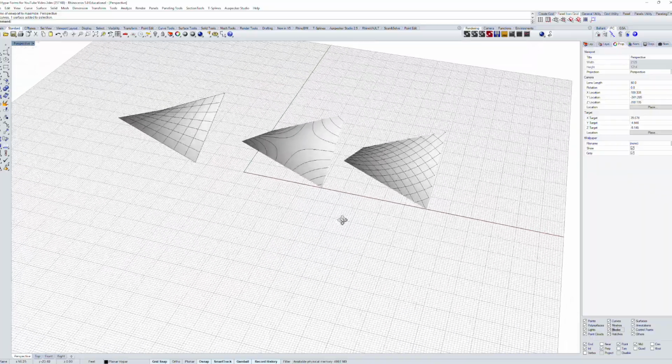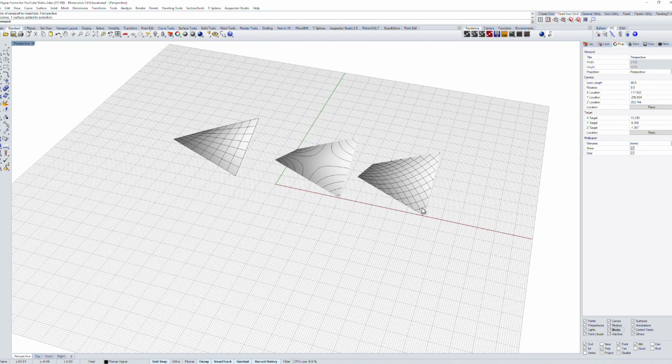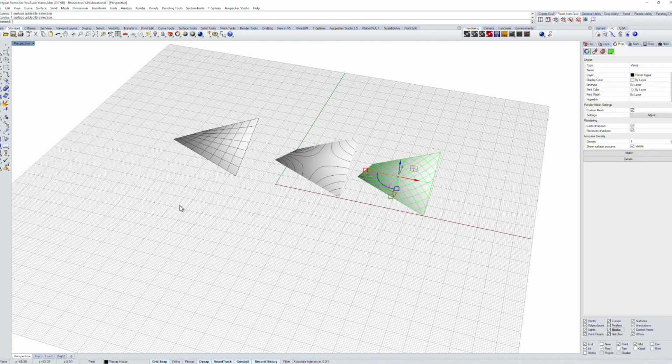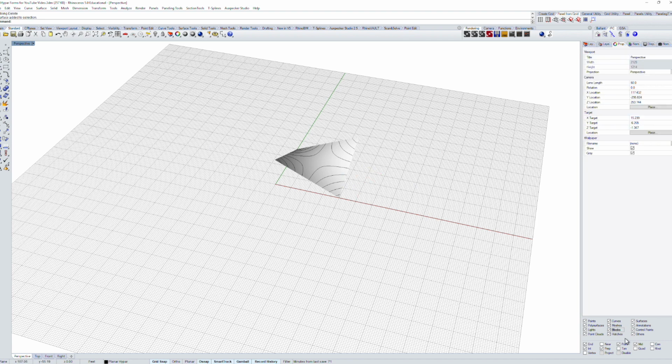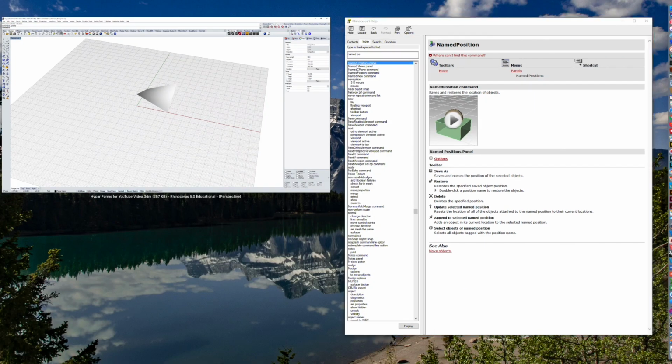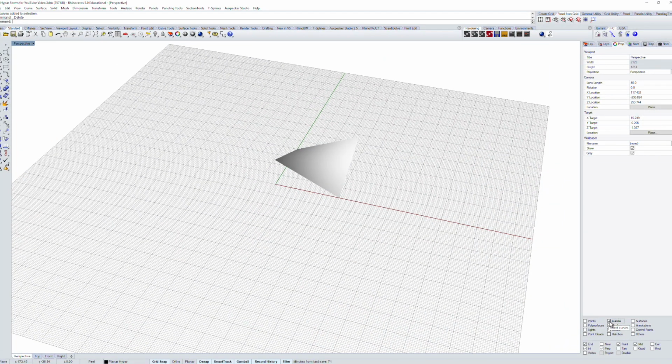So there are fun things that we can do with these kinds of shapes. Let's go ahead and delete these guys here. I'm going to use the filters here. I'm going to filter only curves. That way I don't have to worry about selecting the surface. And by the way, if you don't know this, if you right-click, it will select one or deselect them all. That works for object snaps and for object filters. A lot of people don't use the object filters. It's right down here on the bottom.